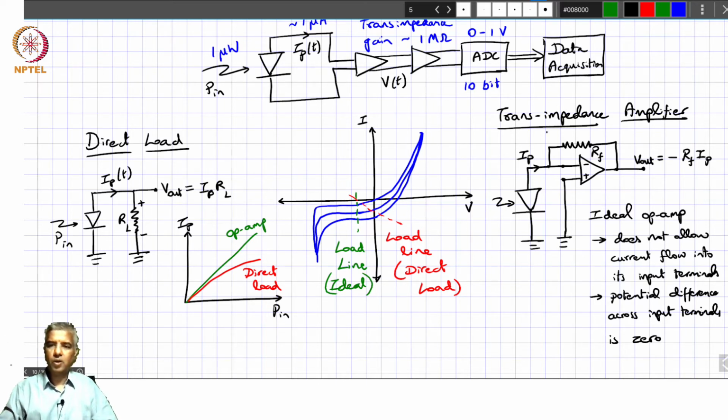You also have to consider a certain feedback capacitance, CF, which could be some spurious, parasitic capacitance that you incur in your board, or the resistor value itself can exhibit certain capacitance. So you essentially have an RC circuit in the feedback.